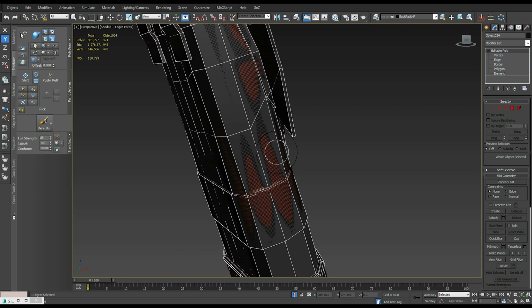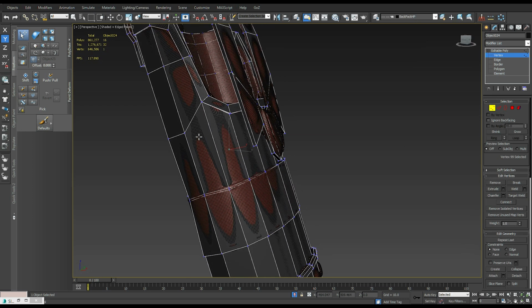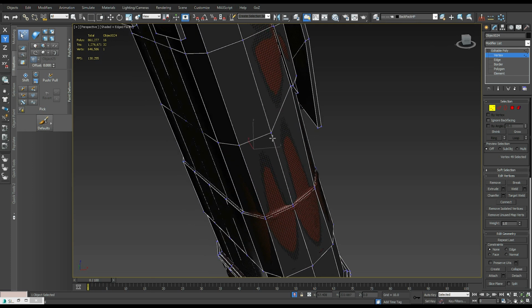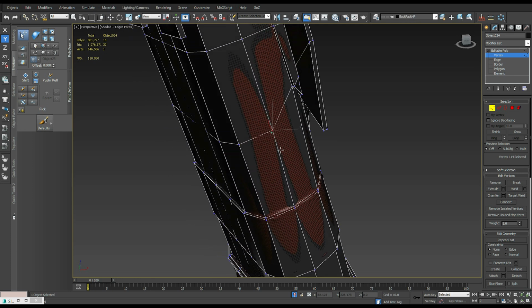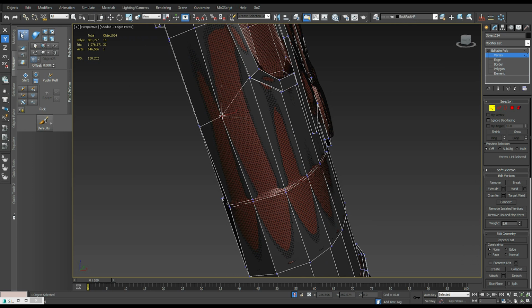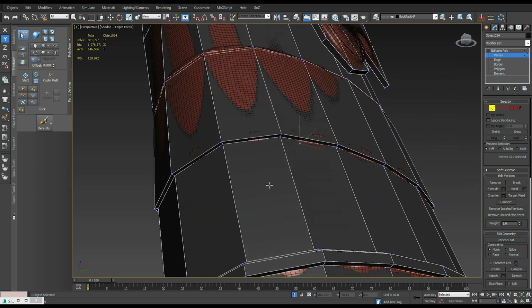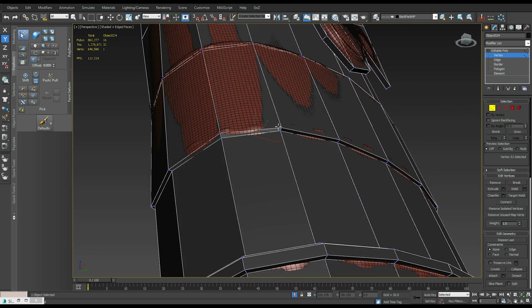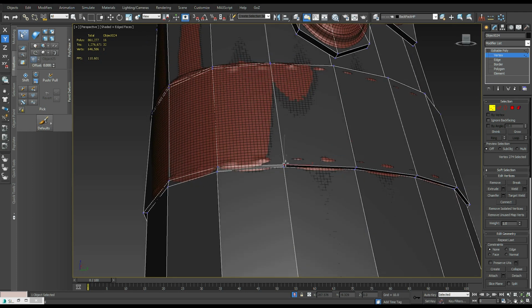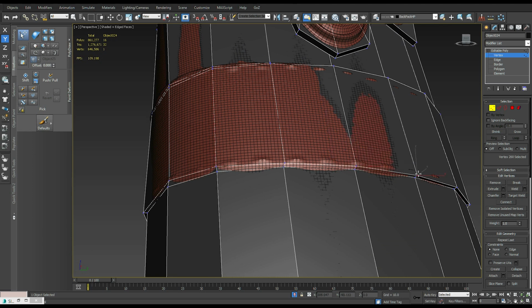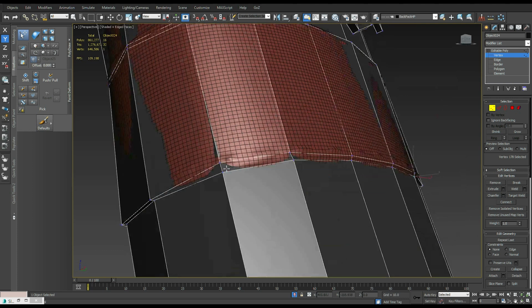The next one I wanted to show you, and I use this all the time too, is right up at the top: drag. It works the same way as the other two tools, but it allows you to move individual vertices right on top of the surface of the high poly. In a case like this, I could come in and start adjusting these vertices, for example, right at that edge where the belt loop was. That's another great example of how this works.